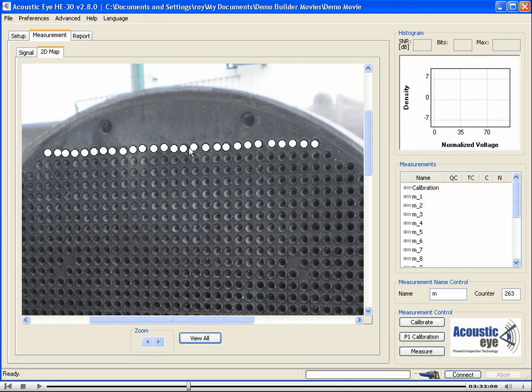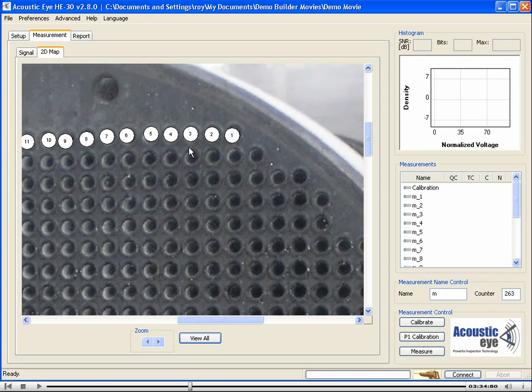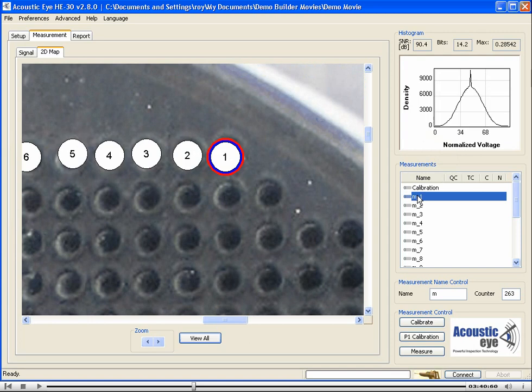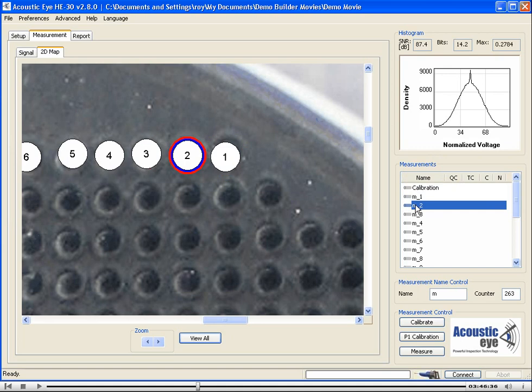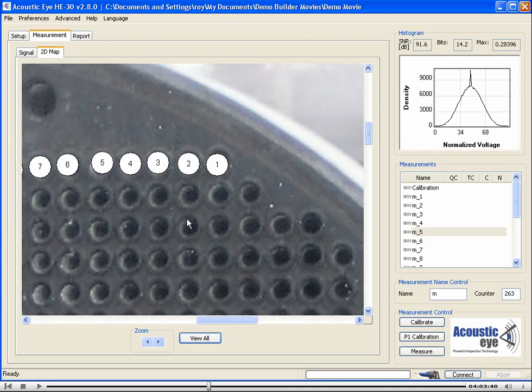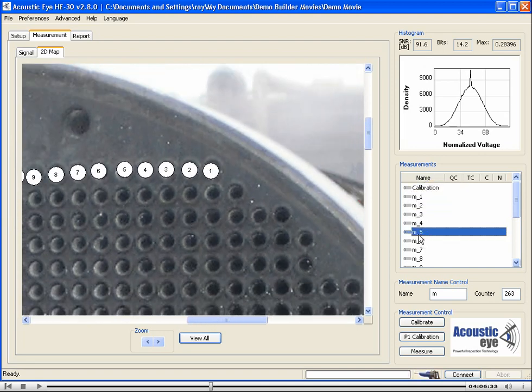Performing a tube inspection using the AcousticEye system is very simple. All I need to do is simply to insert the tip of the dolphin probe into the tube I'm about to measure, and to generate a specially shaped acoustic wave that propagates down the tube. Each change in the cross-section of the tube generates a reflection that is propagating back and captured by the microphone on the probe. The main principle behind this system is that every defect has its own unique signature.